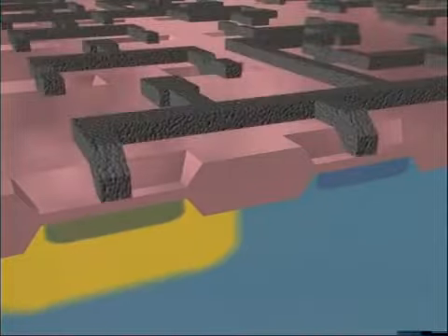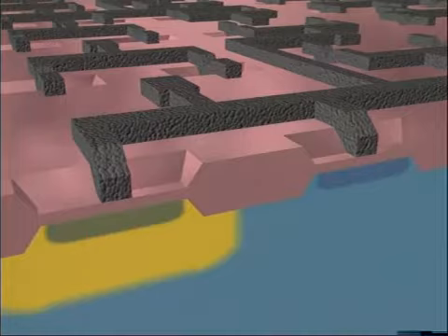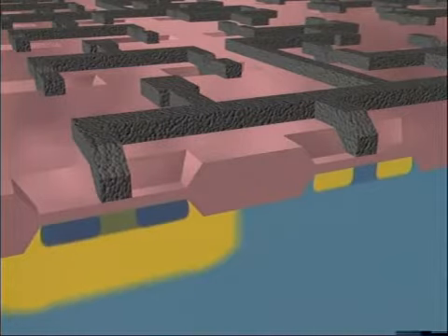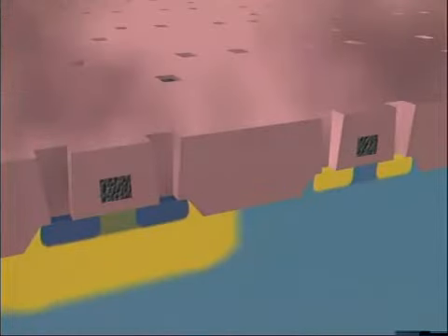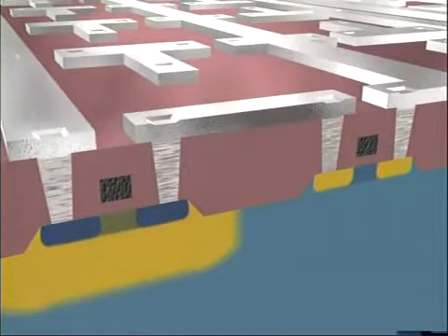Next, the gate electrodes, which turn the transistors on and off, are formed. Masks number 4 and 5 define the source and drain regions of the N-channel and P-channel transistors. The next mask defines the contact holes, which will enable the aluminum wiring used to interconnect the individual transistors to contact the source, drain, and gate region of each transistor.